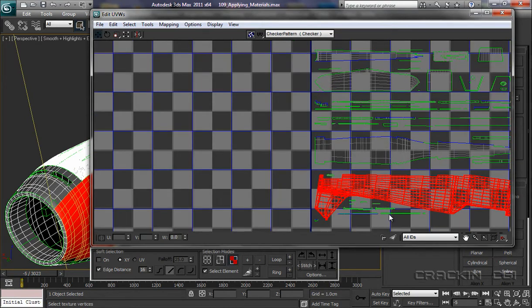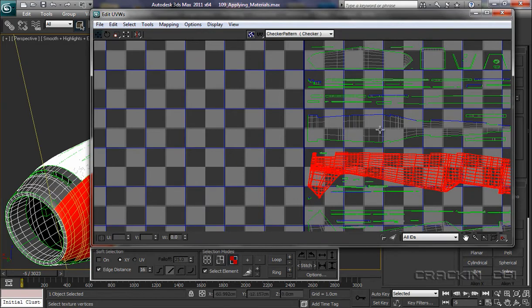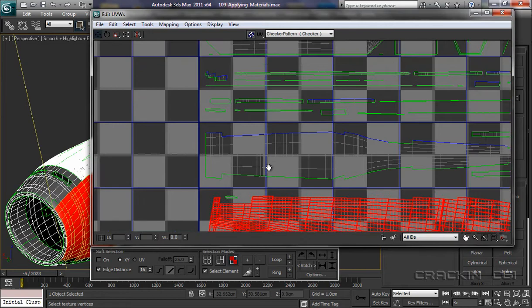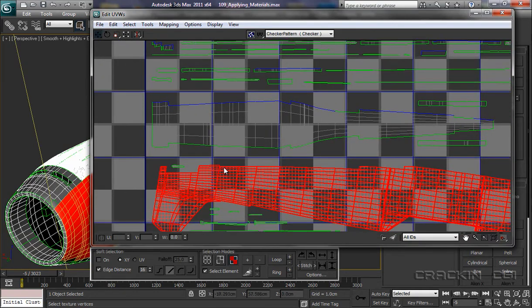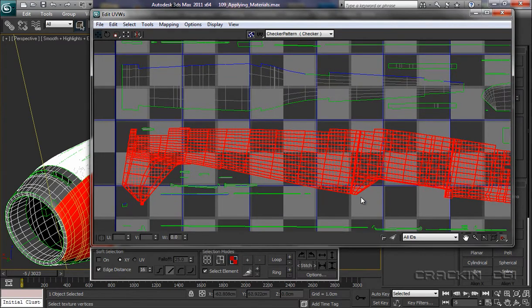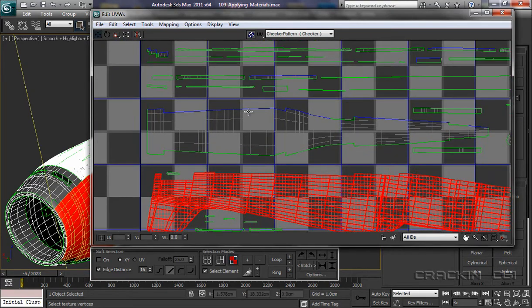Well, in this instance, what I'm looking for is the base of our fuselage, and I can see here that we have this side selected, and along here we have, on this piece of geometry, some blue lines. Well, that's telling me straight away that these areas along here somewhere are connected to that. Now I know there's a break in this section around the cockpit, but there isn't one there, so therefore this has to be the base of our fuselage.